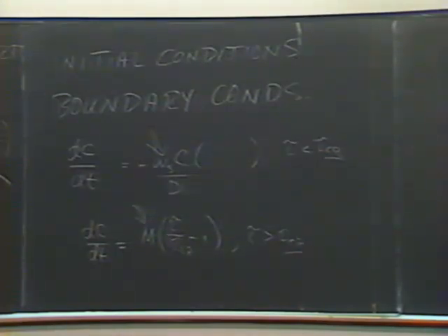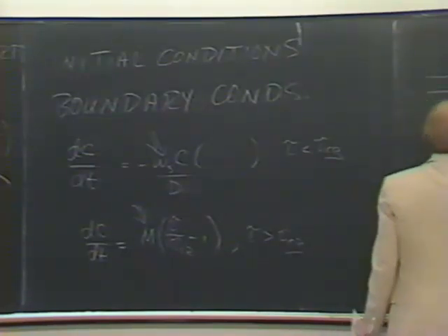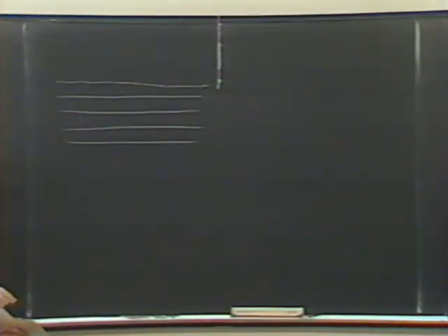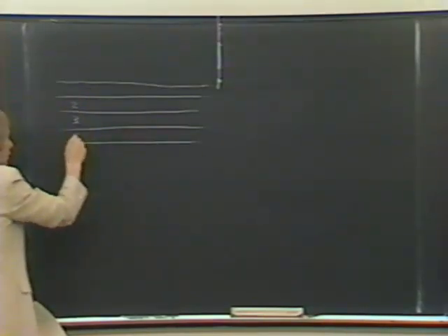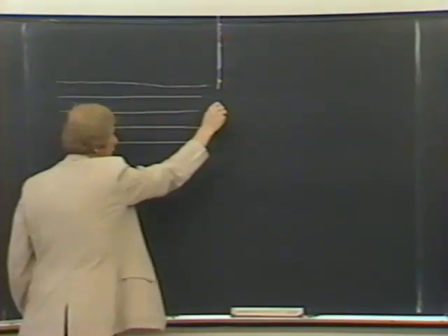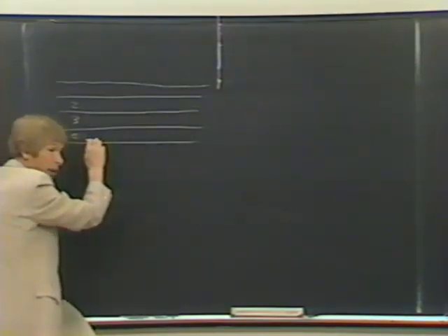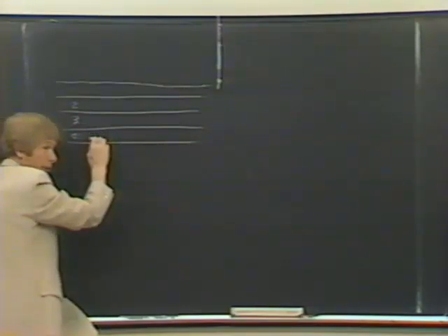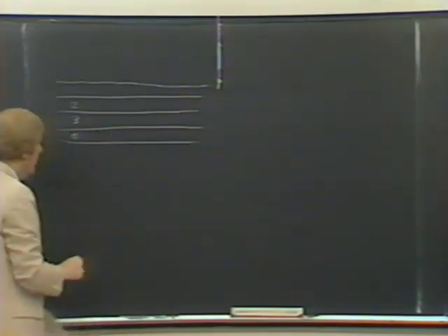So the procedure is to break the bed into layers of whatever thickness your computational system can manage, and to keep track of the layers. So if you have, let's call this 1, 2, 3, and 4, during slack water, these might be, say, 1 centimeter or 1/10 of a foot or some such thickness. If you have all these layers, you have to calculate some kind of increase in strength for this layer, and then these may be wiped off, and then at a later time this might be. So you need to keep track of the layers and the strength. It's a horrendous bookkeeping problem, what it boils down to. It's not an exotic thing at all. It's just a matter of keeping track.